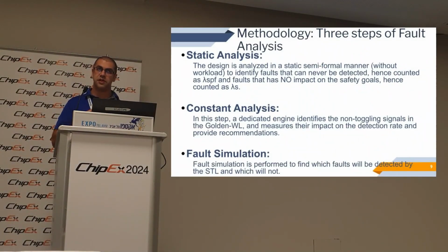The static analysis is kind of a static semi-formal engine. It identifies which faults in the design cannot contribute or cannot influence the safety goals. They have no impact, they have no physical path between them and the safety goal. So this is why we can consider them immediately as lambdas.